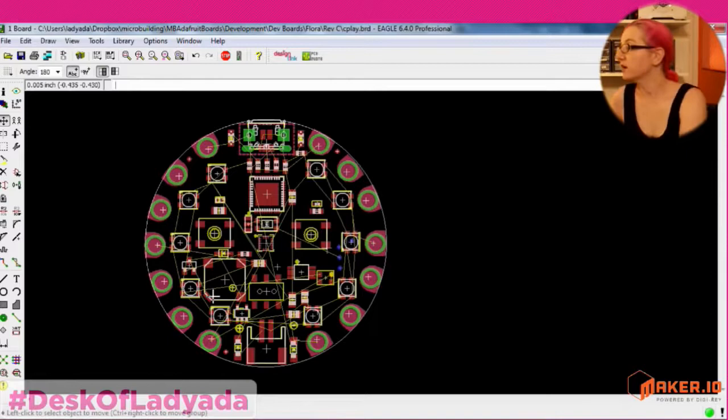Well, it's going to be round because, again, I want it to be round and wearable. So that kind of fixed that. And then, once you pick the side for the micro USB, I wanted it to come up the top. I was like, well, where's the battery connector going to go? It makes the most sense for the battery to hang off, so it only makes sense to go on the opposite side. So then this part's fixed. And then that means all the pads have to go symmetrically on the outside. And the size of them is fixed by that alligator clip.